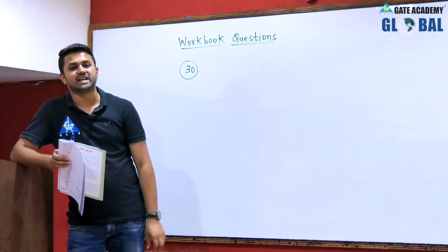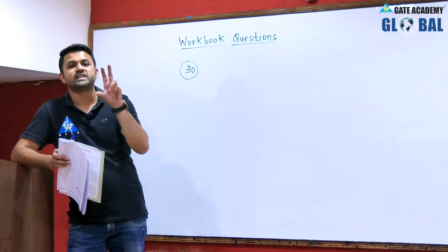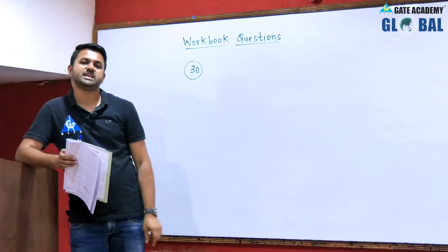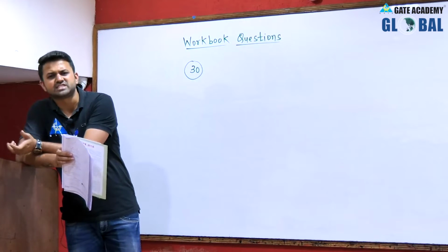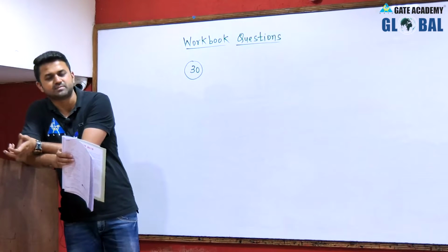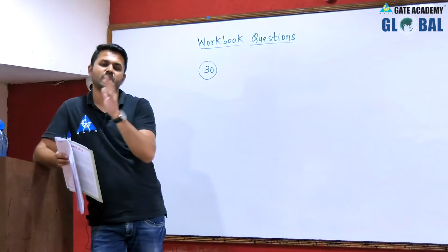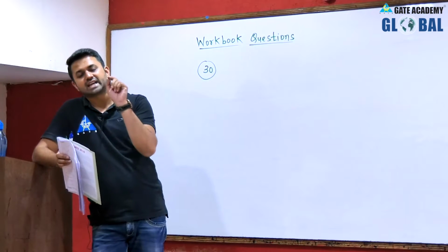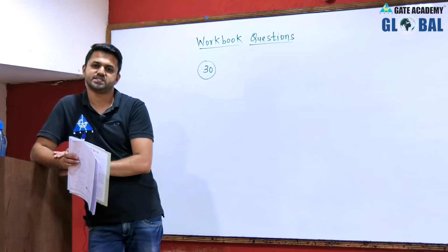It does not mean that the carrier frequency is not there; the component is not there at that particular frequency. The range will be from fc minus fm, which is the lower sideband, to fc plus fm, which is the upper sideband. So the range is from lower to upper, but exactly at the carrier frequency there will be no component, that is, the carrier is suppressed.